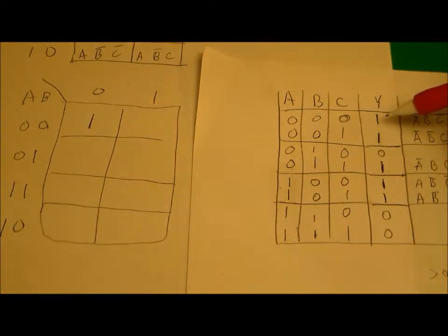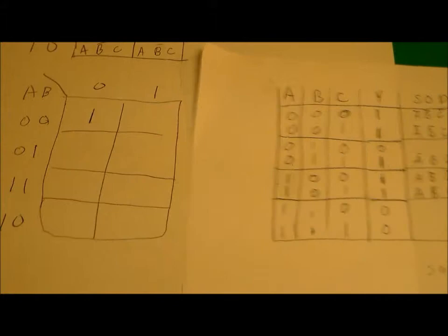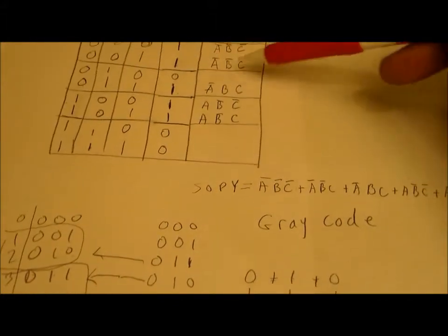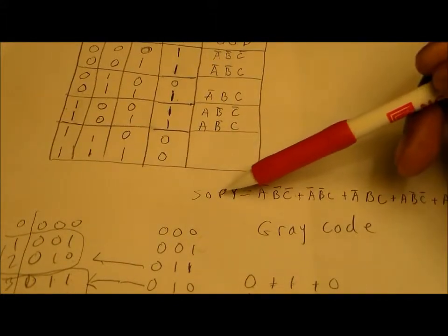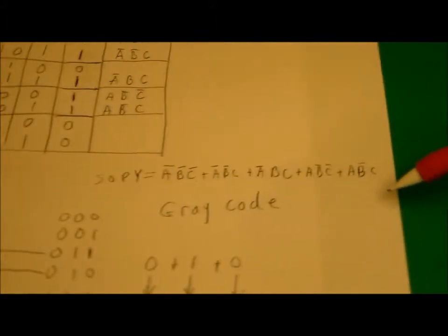What we're doing again is putting together the Karnaugh map, which will help us get a minimum number of terms and actual variables to represent the circuitry that was created by this truth table using the sum of products method, which gave us this really long equation.